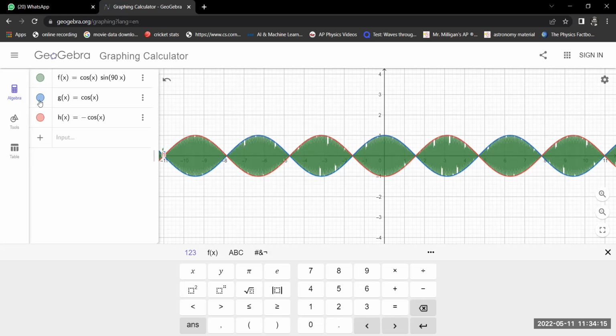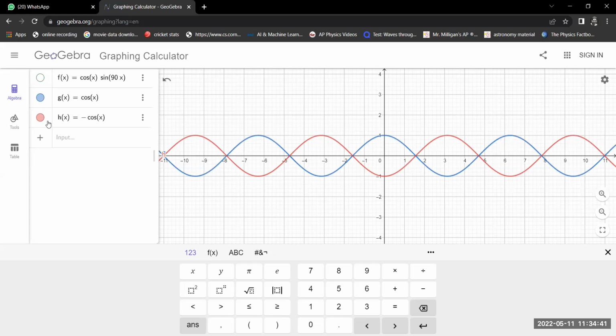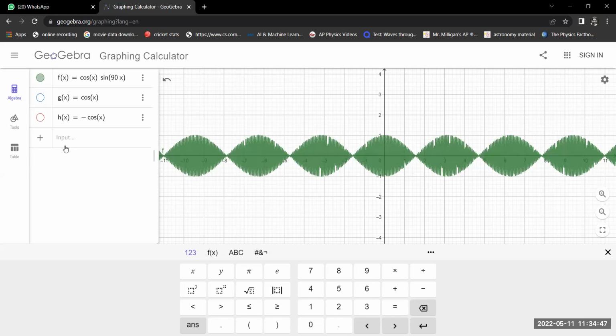So let's say I remove this graph, and this is the only graph, the topmost graph. If I only pick the peak value, which function will the peak represent? The peak of this graph will only represent the cos function, because the peak is the cos x function. If I remove this part and just go to cos x, see, this is only the peak value, right? Yes, sir. In the other way around, if I just pick the peak value, there is something called a peak detector, and if you plot the peak, you regenerate the actual voice signal.